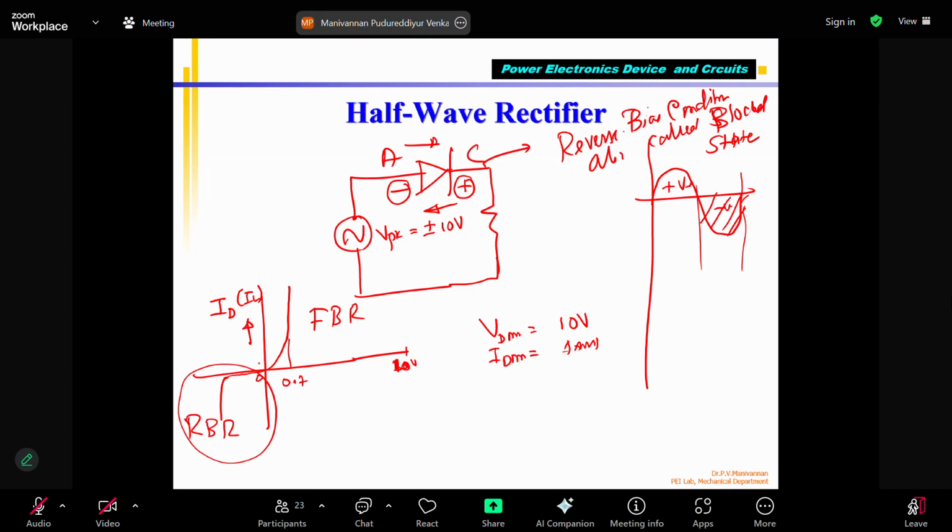Okay. Now, as you increase, 0 volts, this is minus 1 volt, minus 2, like this. As it goes, this voltage is called the breakdown voltage. Okay, the Zener breakdown voltage of the particular diode. I told you the diode maximum is 10 volts. Correct? That means it should be able to withstand plus or minus 10 volts. When I apply negative 10 volts also, this should be minus 10 volts. This is 0. This is 5 volts negative. And the Zener breakdown of the diode, what you are selecting. I think who asked this question?